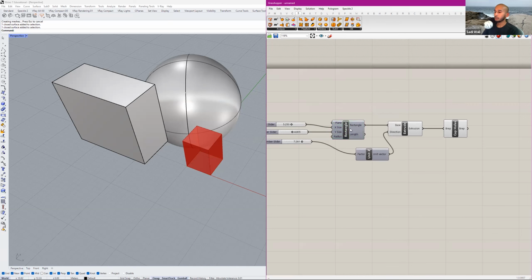You can also disable a component. So that will make it so that that component basically doesn't exist. It's this button here, or you can right click and click on enabled. What this will do is disable the component so it doesn't output anything. And now these components here are orange because the input base geometry failed to collect data. The use case for this is if you're debugging some part of your script and there's another part that is very heavy and time consuming, you can disable that temporarily while you figure out what's wrong with your script, or if you want to preview something.